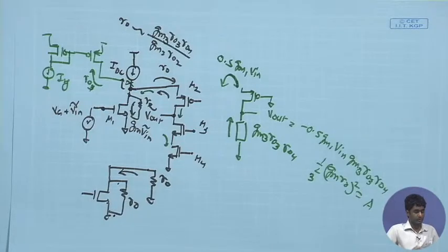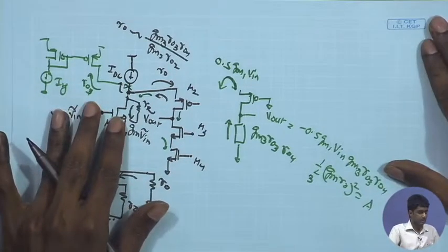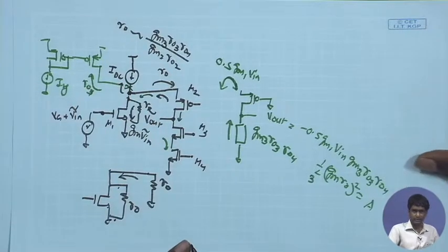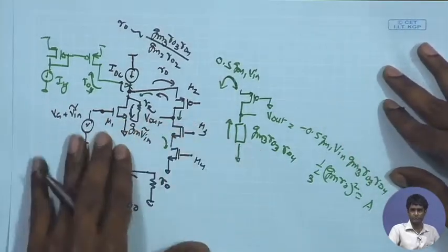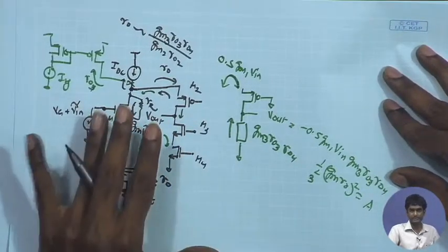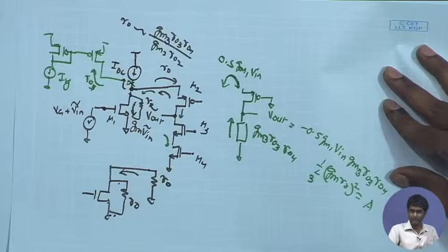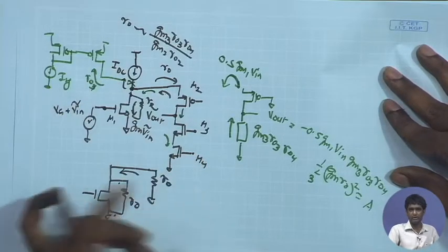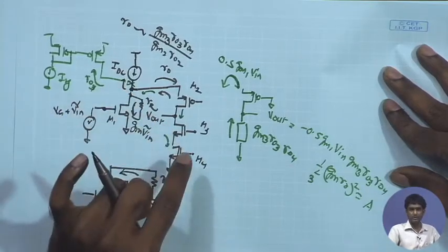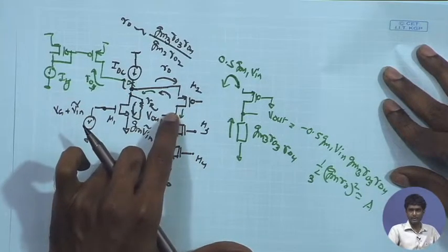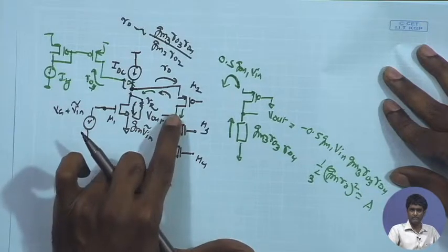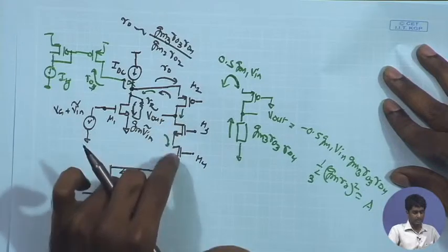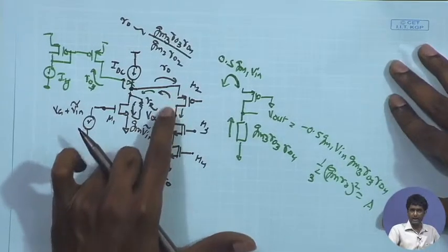Now, once we have this, we can also look at the other factors like the signal swing, DC bias conditions and all. So, let us do that in a fresh diagram. Any question before we proceed and look at the DC biasing, signal swing? From the bandwidth point of view, or frequency response point of view, again we have a similar scenario. Even if we have this configuration, the overall amplifier is going to have this one as the critical or the high impedance node, because if you look at the impedance over here, once again it is going to be the impedance looking upward, Rup parallel Rdown.